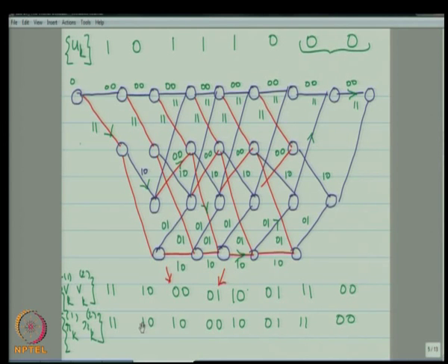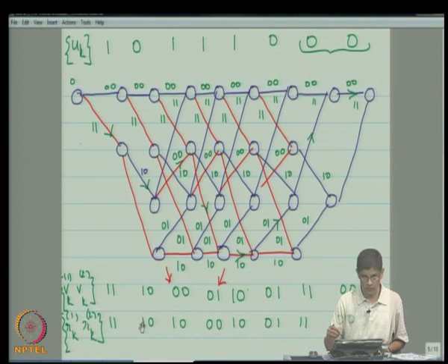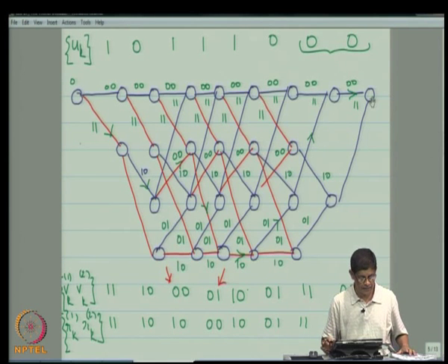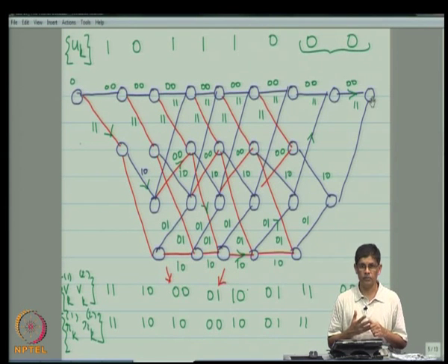So with respect to this trellis, I already pointed out that every path through the trellis which starts at the start node and ends at the end node corresponds to a valid code word. Now, for reasons that will become apparent only later, we are not really interested in all code words, because our goal is to do some path enumeration for two purposes. One is to say something about the Hamming distance properties of the convolutional code, and secondly to do some performance analysis, that is, to develop bounds on the probability of error of a convolutional code. So these are our two goals right now.